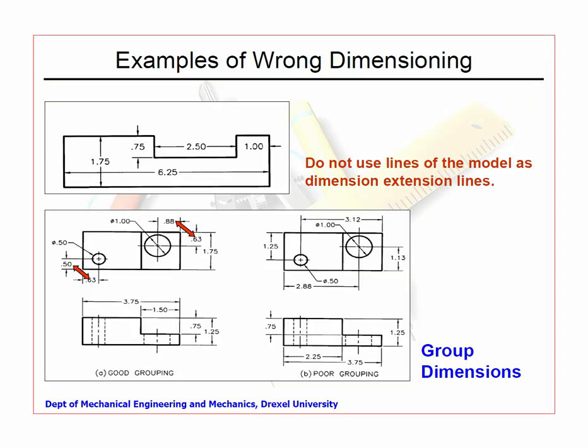And then you see here there is a small step here. Now, there is every chance of the small step being forgotten or ignored in case we try to follow these things here. Now, you see here the various things about how dimensions are grouped well. We are trying to dimension the center point of this. So, things related to this 0.63 and 0.88 have been shown which are related to that. Though technically it is possible that we can put it somewhere else, logically it is not correct.